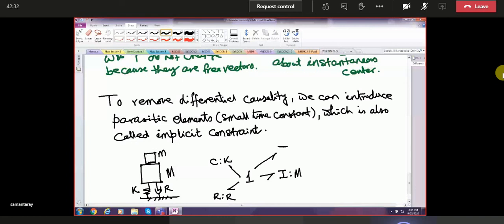Sir, I was saying one had integral and one had differential causality, right? So when you are reducing the transformer, using that M R square, you added both terms. How can we add when they have different causalities? You can add, no problem, as long as they have the same velocity. So two masses having the same velocity are one mass.